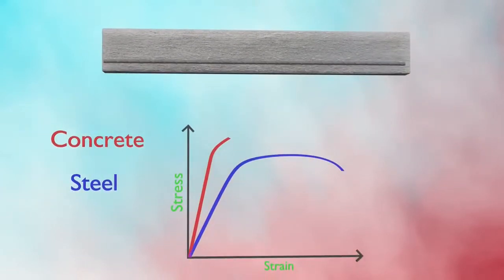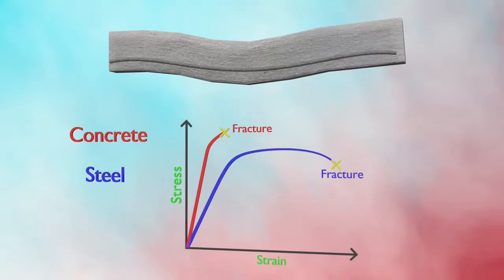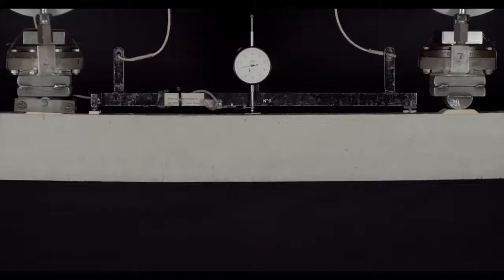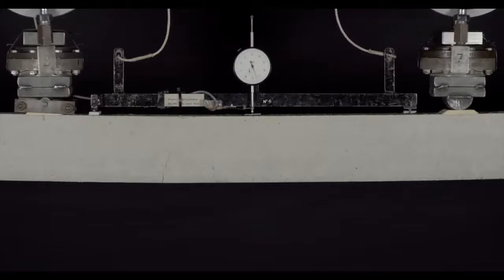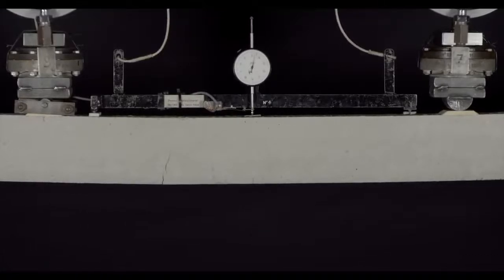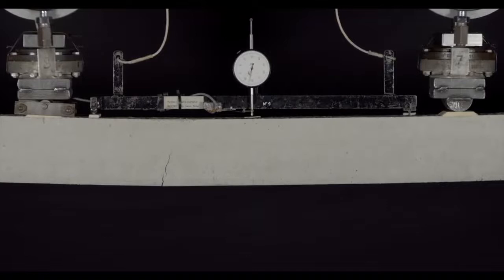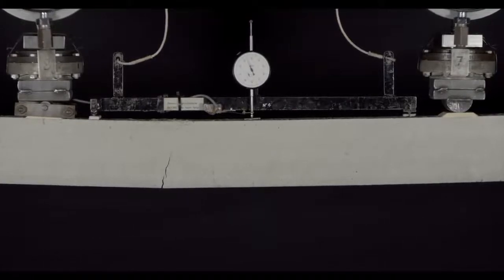Therefore, the steel provided at the bottom of the beam will give a warning before it fails. This is what we know as yielding of the steel. So the steel is going to yield before the beam fails. You need to understand that yielding of the steel in an under reinforced beam does not mean the beam has failed. When yielding of the steel takes place, there will be excessive deflection and cracks will appear in the beam before it fails. This gives at least enough time for the people inside the building to move out before the beam fails.